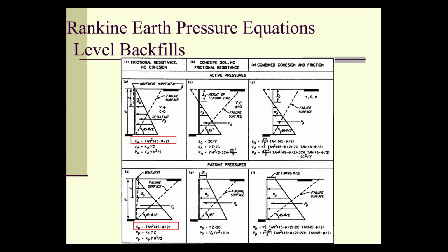And then, looking at the column to the left, sigma A is equal to Ka times sigma Z, and that's basically all that says: that's the active pressure at any point Z along the wall. My notation here is a little clearer than it was before. And then the total pressure, we integrate the whole thing, is Ka gamma H squared over 2, which I just looked at with at-rest theory.